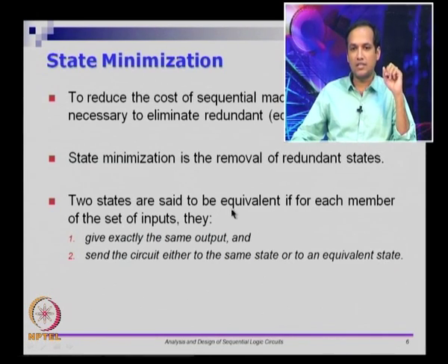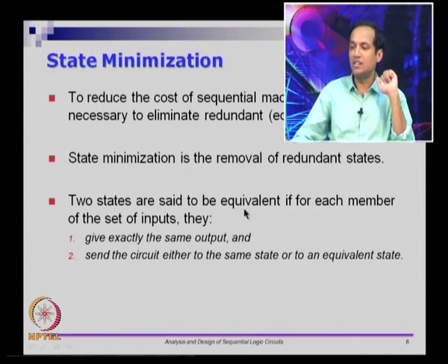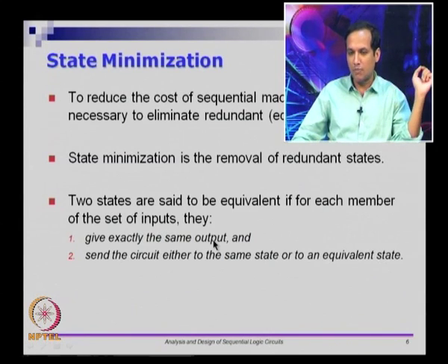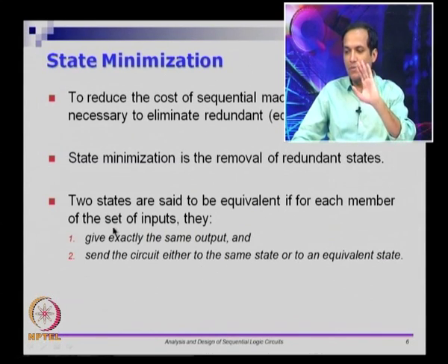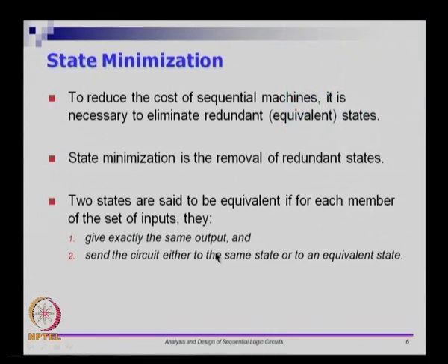2 states are said to be equivalent in a single state machine if for each member of the set of inputs they give exactly the same output and send the circuit either to the same state or to an equivalent state. So this is a loaded definition, but we will see an example in the next slide. This will make it clear.